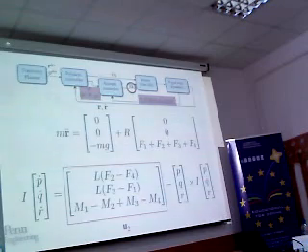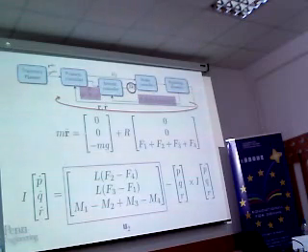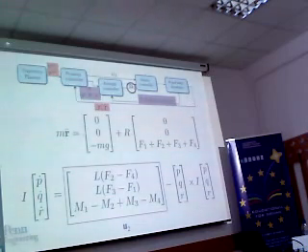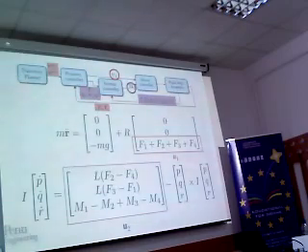We now turn our attention to the outer loop, which is a position feedback loop. In this position feedback loop, we look at the specified position vector and the specified yaw angle. We look at the actual position and the actual velocity. And from that, we calculate U1. So we will feed back the R and R dot in order to calculate U1.